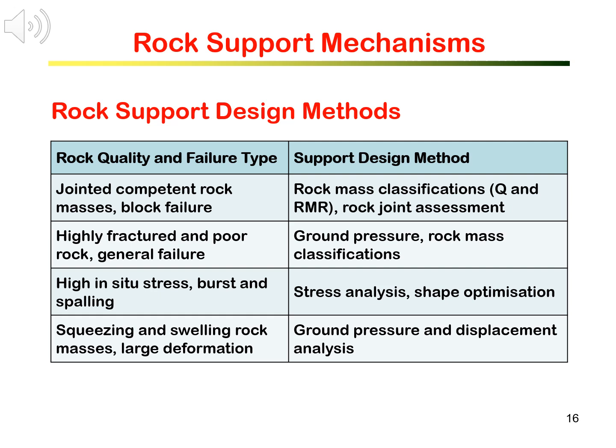To design concrete lining, steel ribs, and pillars, we generally need to estimate ground pressure in order to design the support as load-carrying structures. For deep tunnels and mines, stress analysis must be conducted. Support design will be based on the amount of stress to be carried, and at the same time, opening shape may be optimized to minimize stress concentration and reduce the support requirement.